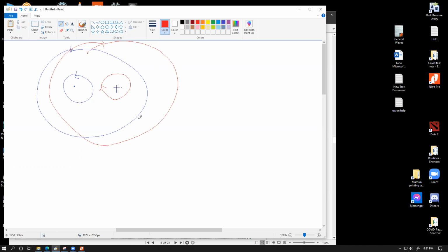So what you should be seeing is that for the in between space they are producing similar direction magnetic field, but for the outside, here the red is going downwards, the blue is going upwards, and over here the blue is going downwards, the red is going upwards. So for all of the outer space over here and over here as well, the magnetic fields will be pretty much counteracted by the opposing magnetic fields produced by each other. However, for the in between space exclusively, the magnetic fields would become stronger.